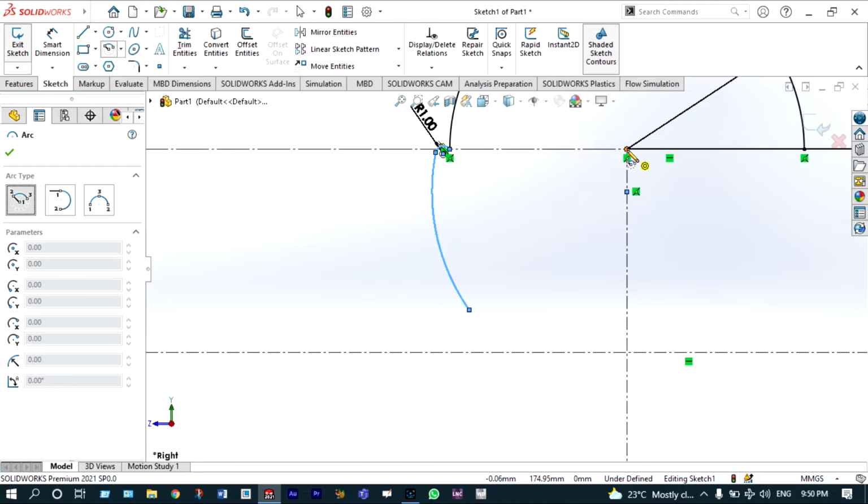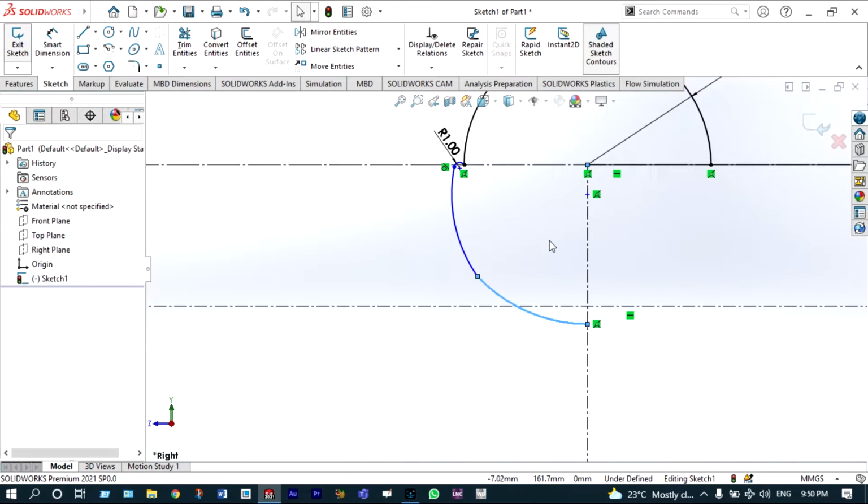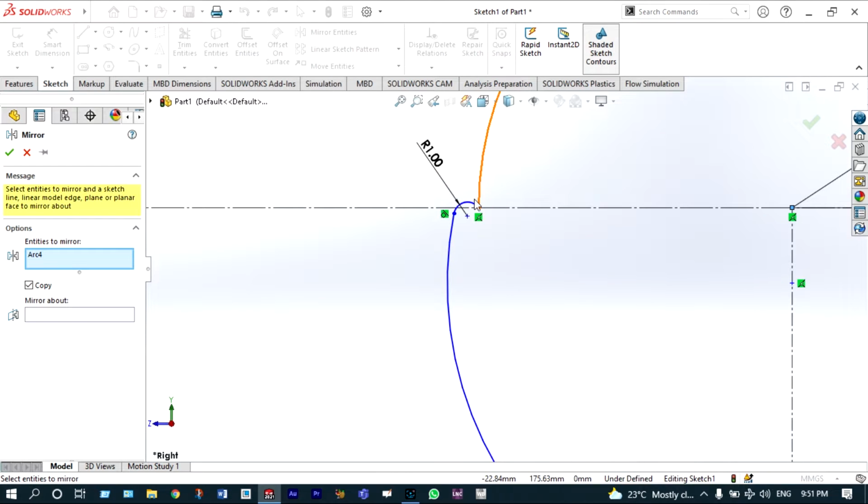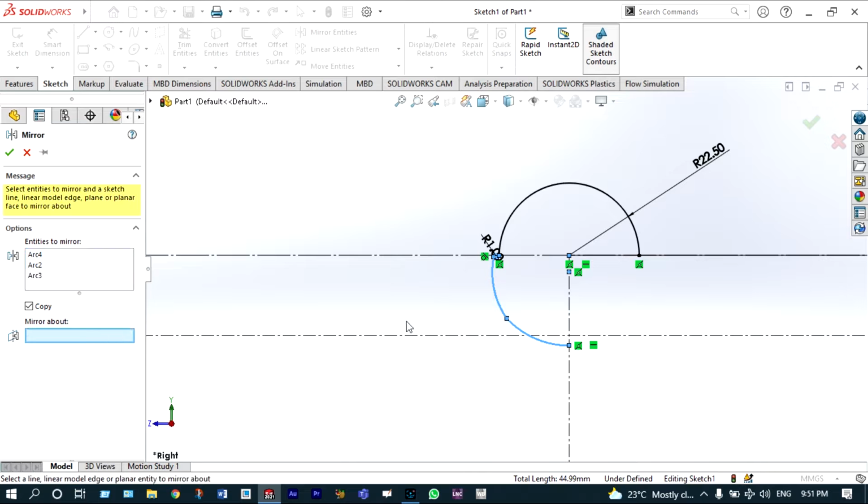And this part, the circular section, should be added at this location. That can be initiated from the center itself. At this location, you have to provide a little bit of flat section. So we can provide these mirror entities at the right hand side. You can select those entities and they are to be mirrored with respect to that central axis. Done.